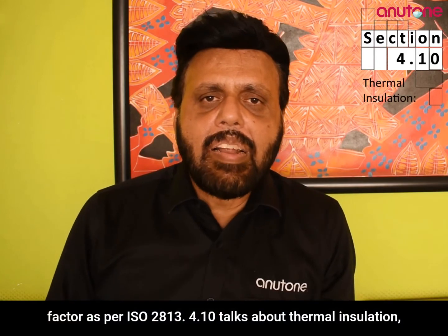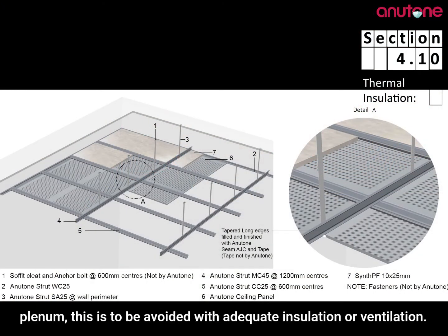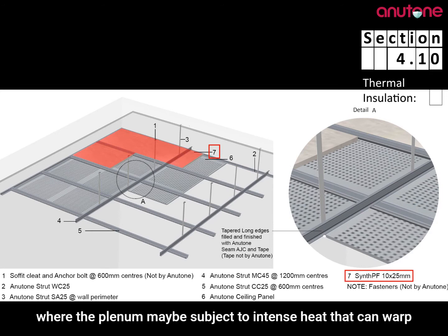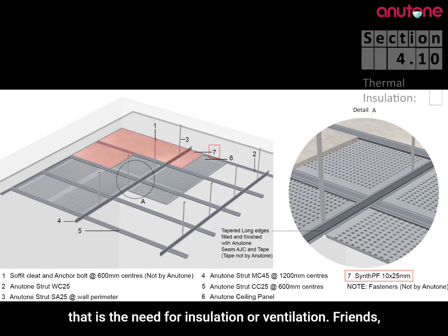4.10 talks about thermal insulation, where there is risk of condensation under a cold roof or plenum. This is to be avoided with adequate insulation or ventilation. Similarly, for very hot metal roofs, where the plenum may be subject to intense heat that can warp and sag the ceiling tiles, there is the need for insulation or ventilation.